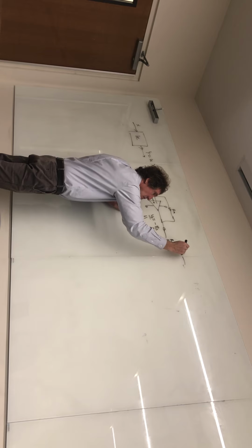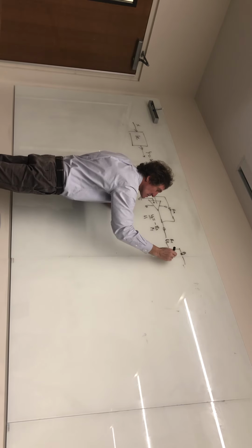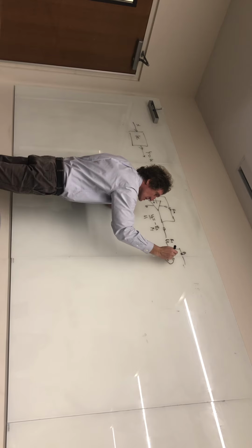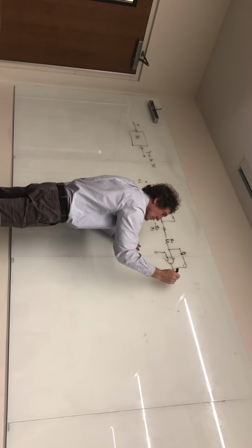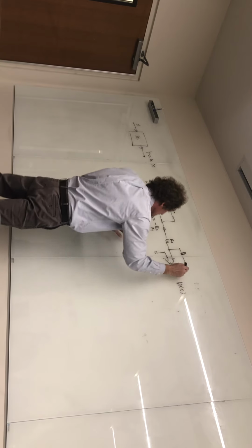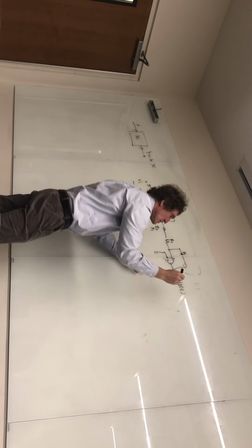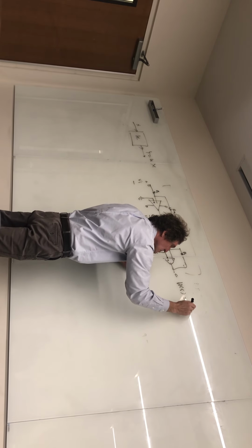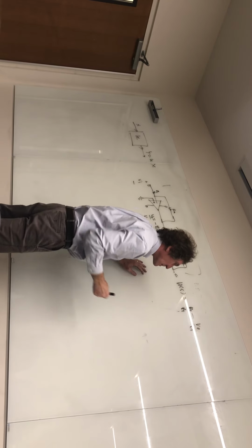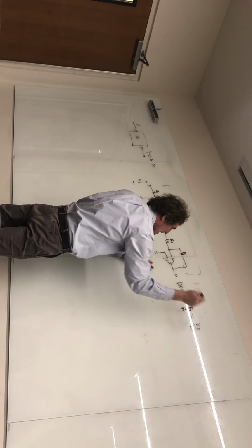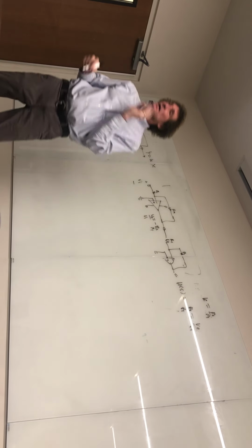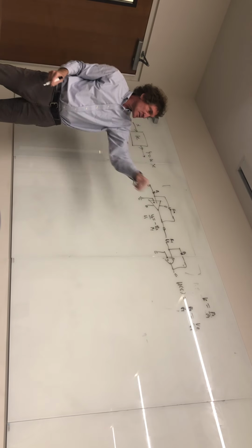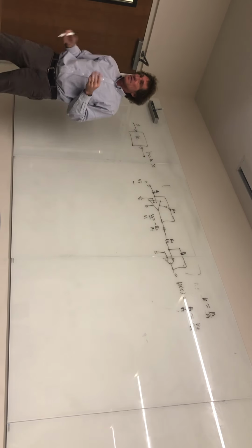It doesn't have to be R1, but it can be. And it goes into the operational amplifier. I mean, this is really an inverter. And now my output transfer function, H of S, for this entire circuit right here is equal to simply R2 over R1. And that's simply equal to the ratio of V out over V in. Therefore, the constant K would be R2 over R1.